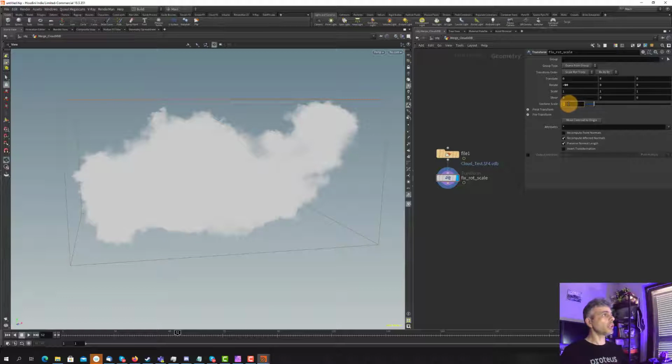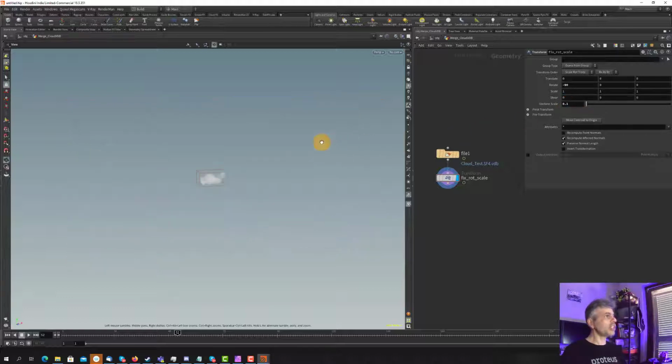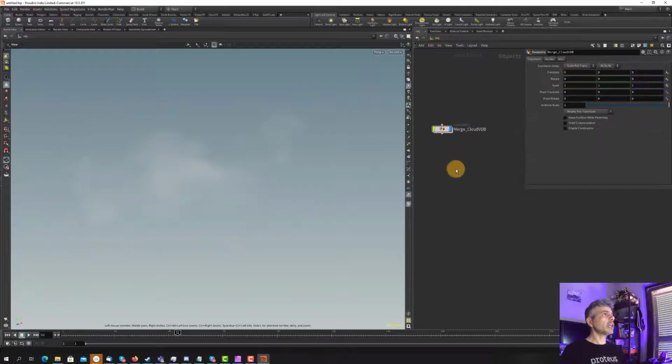So you see we have the same orientation we had in Embergen, and the scaling can be 0.001, which will be the perfect one, but 0.01 can be nice because the scaling is interesting. Okay, let's set it to 0.01, because in this way we'll have the same rendering we had before. You see that now it's really little, because we are talking about meters, so the density is low. We have to take care about the density later in the rendering.